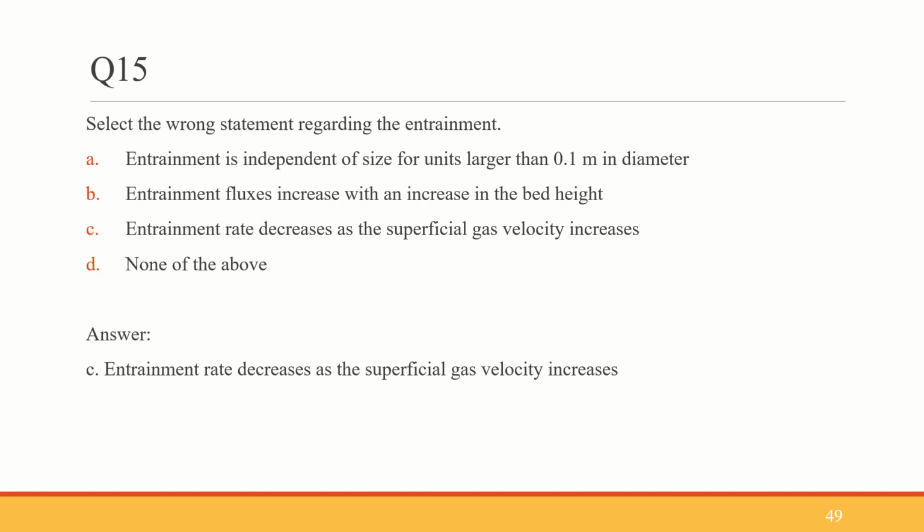And third one, entrainment rate decreases as the superficial gas velocity increases. As the superficial gas velocity increases, the entrainment rate increases. When velocity is high, the carryover of the particle is high. So entrainment flux increases as the superficial gas velocity increases is the right statement, whereas the one given over here is a false statement.